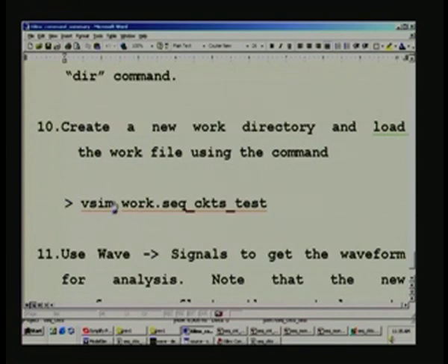Vsim is the command for the simulation, and it is actually for loading the design file, because we have compiled with the back annotated file, and that corresponding file will have to be loaded. That is what we say, whenever you have a compilation it should be followed by simulation, and that is what we do here, and naturally that is in the work directory, and the name it has is precisely the same as your top module, which is the test bench, which includes the back annotation file.